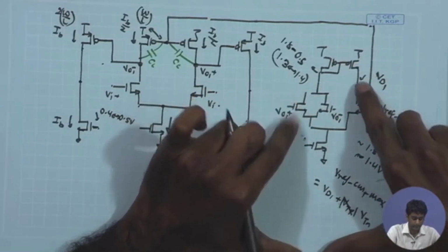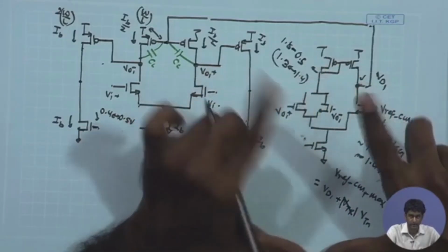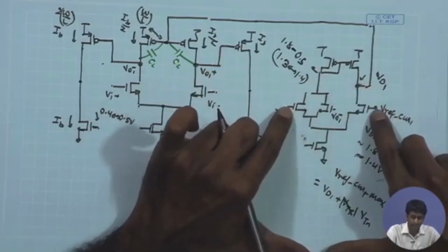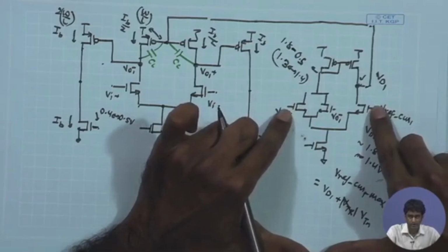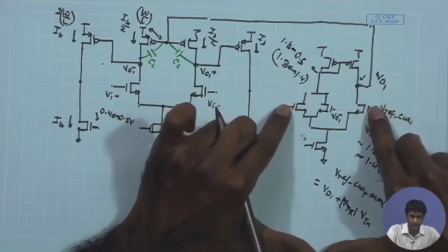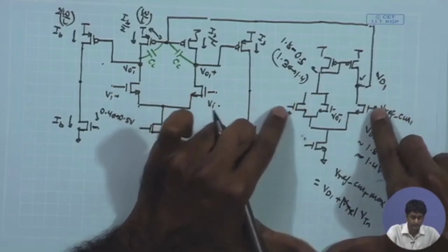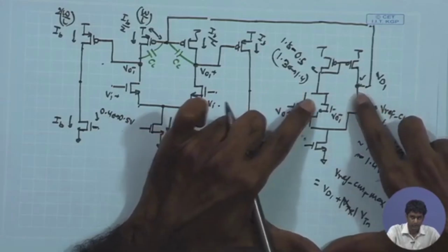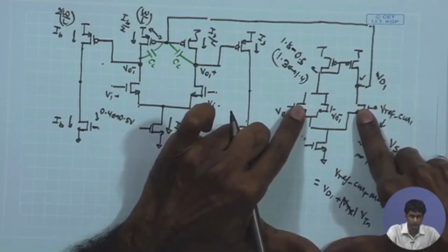from the maximum side this drain potential is being clamped with the help of the direct connected MOSFET, and for that particular drain potential I am just seeing what is the maximum allowed VCM ref that you can put. If you go on increasing the gate potential further and further, what is the maximum gate potential that you can have while keeping this transistor into saturation? That is going to be the drain potential plus Vt. Beyond that, the transistor over here will be entering into triode region.